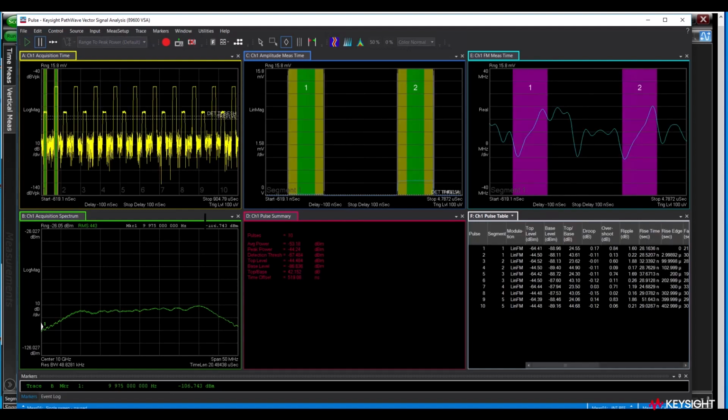Okay, so here we see these small radar echo and large jammer pulses being pulled into segments. Okay, and depending on how close together they are, they may go into one segment, they may get their individual segments, but the scope's making a decision for how to efficiently pull this information as IQ data into memory and then allow measurements to be made.